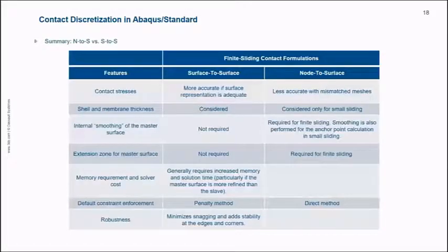All right, so just a summary of surface-to-surface versus node-to-surface, and you can get the recording for this and pause it here and take a screenshot of it or whatever. You can have that. And if you read through here, you would see the differences between surface-to-surface and node-to-surface, and you might come to the conclusion that, yeah, surface-to-surface is what I want to be using. And as I said earlier, you can get access to this algorithm through the general contact framework, which is what I would recommend today in Abaqus Standard.